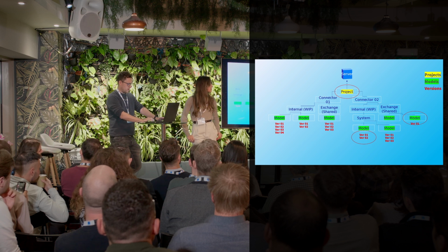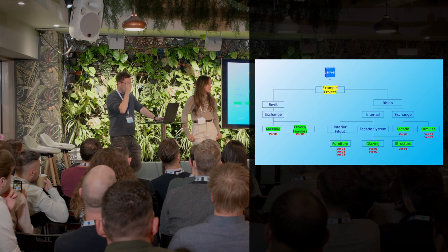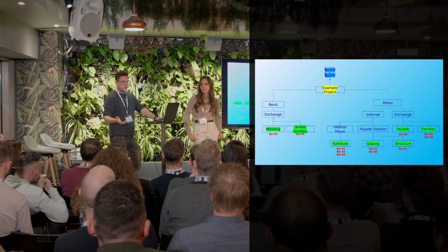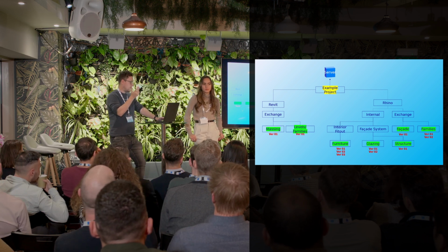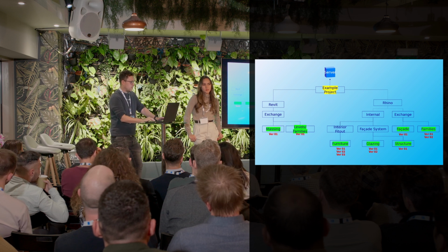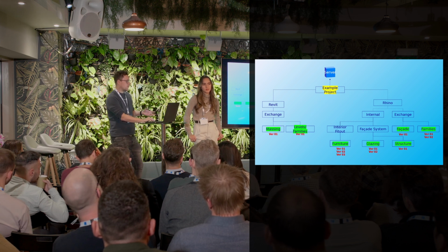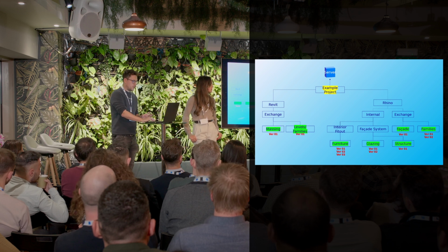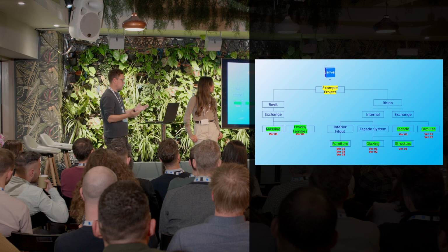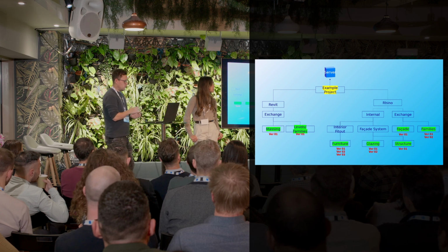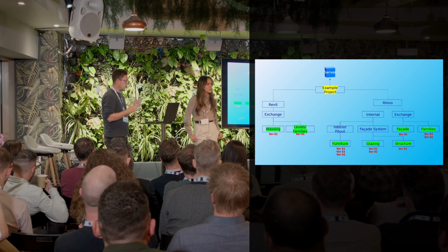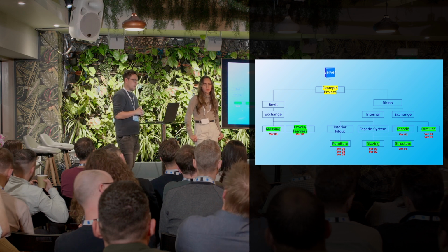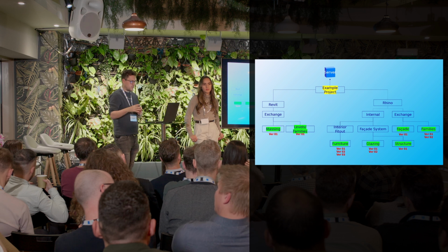So to do a real life project example, we have an example project here. On one side, we have Revit. Again, we don't need internal because they already have the collaboration feature that you can sync. But maybe we just want to extract the massing or levels and families and exchange that across. With Rhino, you may have an internal folder and an exchange folder. Internal, again, maybe you're just developing furniture, or maybe you're doing some kind of facade system and you're just playing around with it, trying to get ideas inside your team. And then when you're ready to send it back to Revit, you put it in this exchange folder.